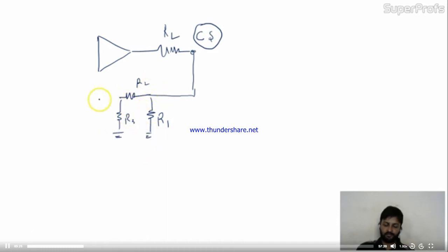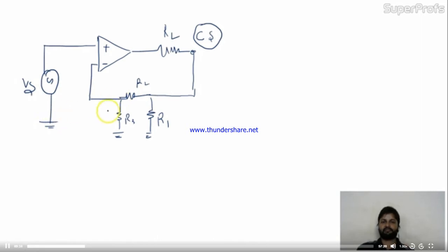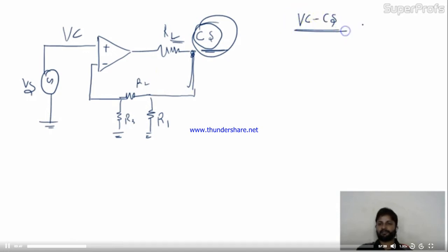This is the feedback box. Over here, it's going to minus. And at the positive terminal, we applied a voltage source. So which type of topology is it? At the input stage, it's a voltage control. At the output stage, it's the current source. Why source? Because after the load, you are taking it. So I can say it is voltage control current source.